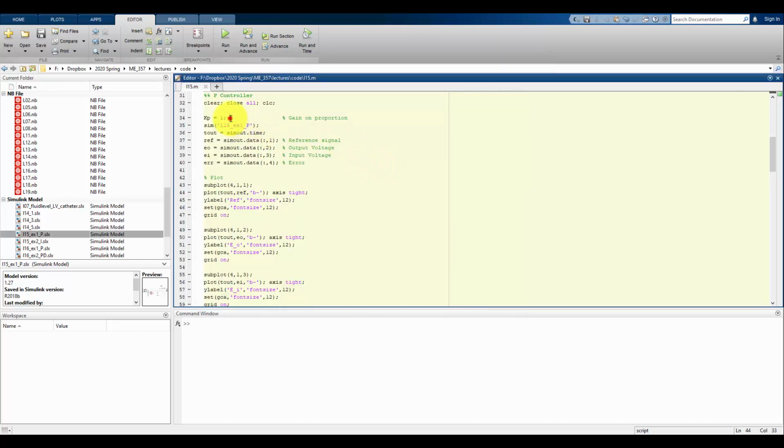So I'll run this through MATLAB, and first I'm going to try, like I discussed before, what if the gain is just 1? So I'll set my Kp equal to 1 and run my sim. Once Kp is set, it's going to run my exact schematic with a gain of 1. And then, like we saw before out of Simulink, we're going to get this sim out, and I'm going to part it out because I know what each column of sim out data is going to be.